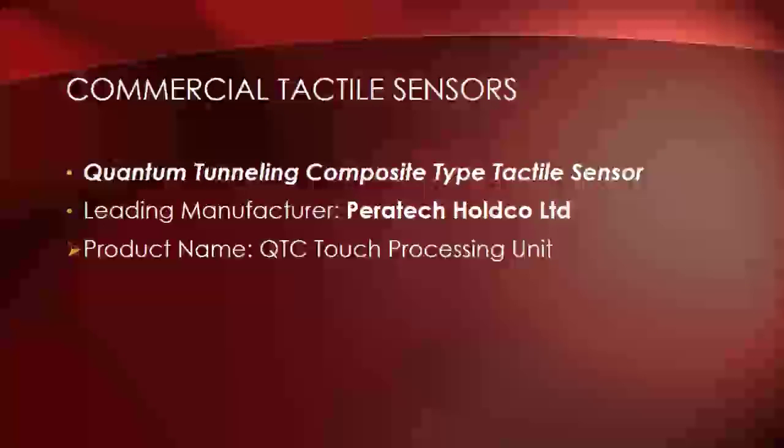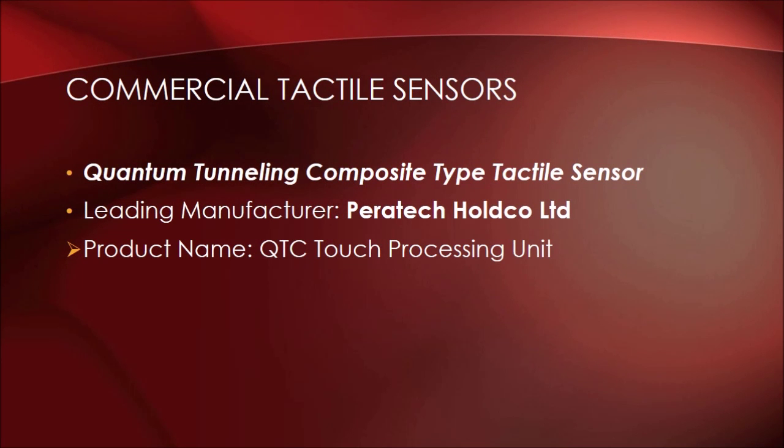The last commercial sensor that we are going to cover today is the quantum tunneling composite type tactile sensor, whose leading manufacturer is Peratech Holdco Limited, and the name of the product is the QTC Touch Processing Unit. Quantum tunneling composites, or QTCs, as mentioned before, are composite materials of metals and a non-conducting elastomeric binder. At normal conditions, that is, without pressure, they act as insulators, and when pressure is applied, the resistance decreases exponentially.